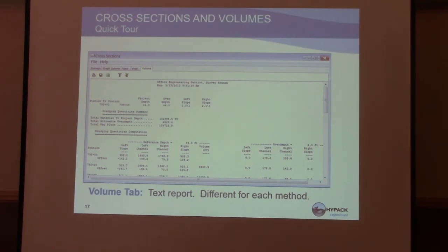I use the cross-section sheets through TIN. Okay. I mean, the line file, and then just do the 2D cross-sections in the TIN model. Yeah, and then just print it that way in PDF. Okay. And that's one we talked about in the previous session. Okay. With the TIN model with the planned lines across the cross sections.